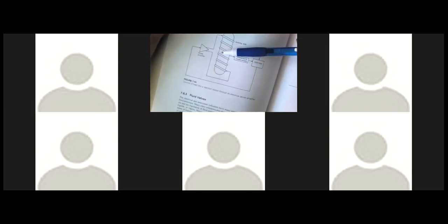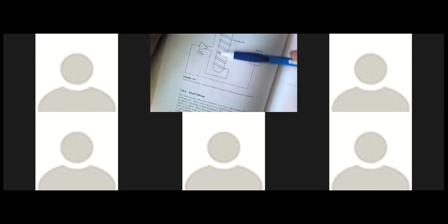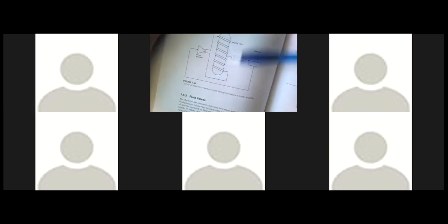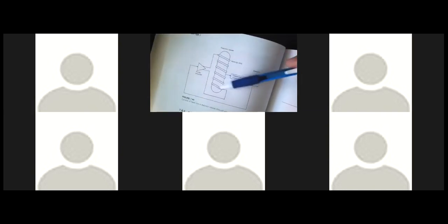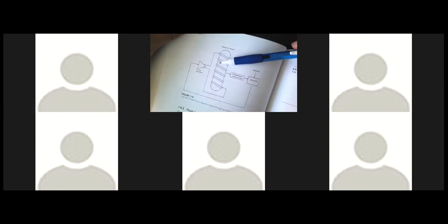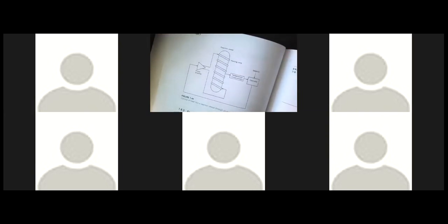So the last, this is another example. They also did a PID controller to control the temperature. Again, temperature control. This is another temperature control. The PID controller will control how much, for example, steam, the heating coil. This is an electrical actuator. The actuator, not electrical actuator, the electrical final control element. The final control element is an electric heater. So that's the last example. Electric heater as the final control element.